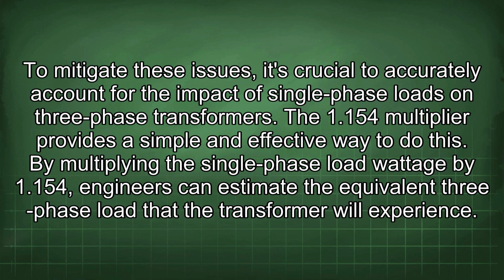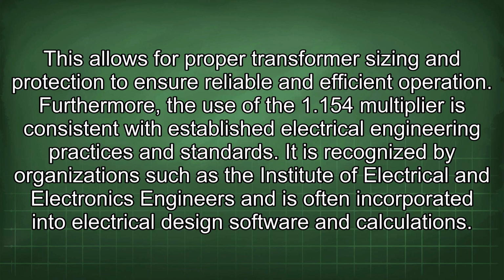To mitigate these issues, it's crucial to accurately account for the impact of single-phase loads on three-phase transformers. The 1.154 multiplier provides a simple and effective way to do this. By multiplying the single-phase load wattage by 1.154, engineers can estimate the equivalent three-phase load that the transformer will experience. This allows for proper transformer sizing and protection to ensure reliable and efficient operation.